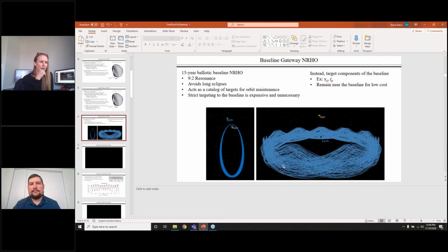And you can step through that ephemeris. It's very fast if you minimize your screen. If you want to watch it go, then it's a little slower. It just depends on what you're after. You can't just grab an initial state off this and propagate it with an RK89 for the whole 15 years because it is mathematically unstable. Even if your errors are 0 and you use the same script and the same setup to generate the orbit as you're going to use to propagate the orbit, it's still going to diverge over time due to buildup of numerical errors because it's a mathematically unstable orbit. So even best case, after 14 revs, 14 weeks, it's going to escape from the NRHO,